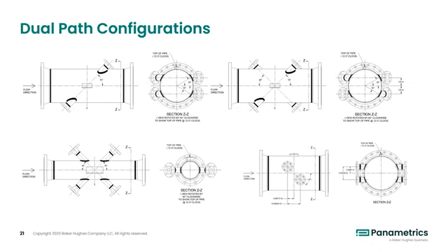The first three of these images are various configurations of straight head or 180-degree applications, whether that is a T5 or a T17 transducer. The image on the bottom right shows two T5 bias 90 applications on opposite sides of the pipe.